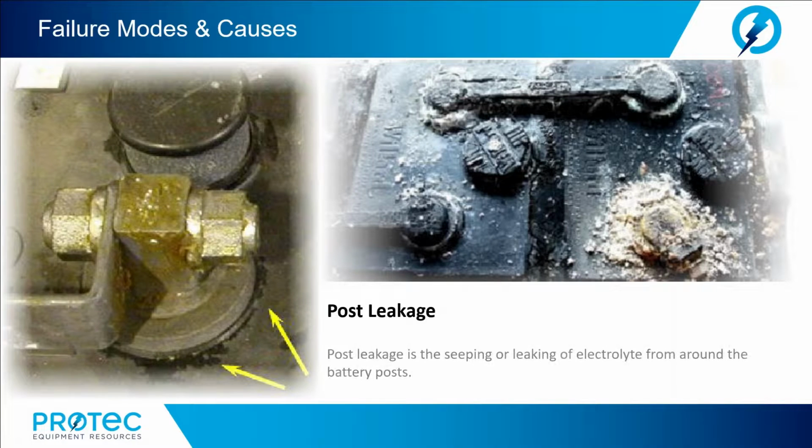Post-leakage. Post-leakage is the seeping or leaking of electrolyte from around the battery posts. Post-leakage is unsightly and it should be cleaned as found. Post-leakage left in place can lead to post-corrosion, which then can lead to a cracked cover or jar.